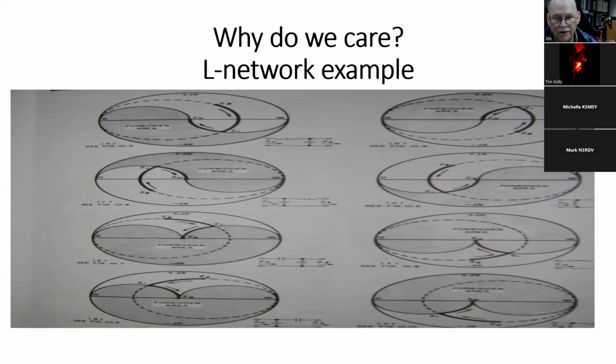But down here, a parallel capacitor and then a series inductor. Notice the capacitor is up front instead of downstream. Will get you there. So with these two circuits, you can match any impedance. And there are other variations thereof.